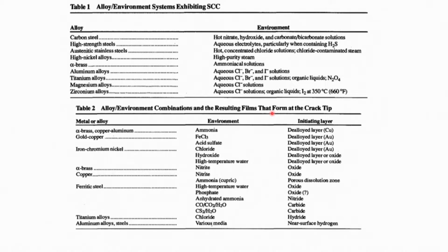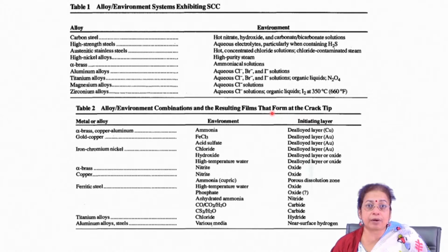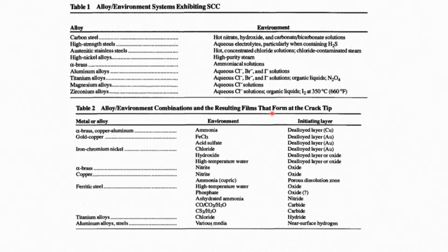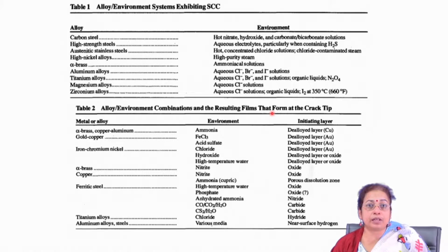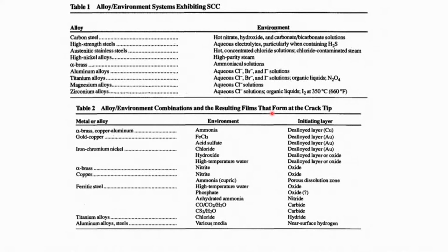It is very important to know why this stress corrosion cracking behavior is environment specific, because it has been observed that the main reason behind stress corrosion cracking is the selective leaching of the typical passive film which forms on the surface. Whenever there is leaching of the passive film, that zone acts as a site of microgalvanic attack, and where stress is very high, stress concentration occurs. So, it undergoes dissolution at a much faster rate. So, the environment is one where there is breaching of the typical passive film.